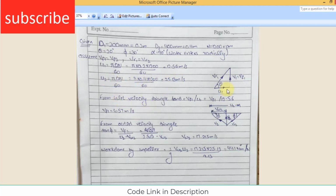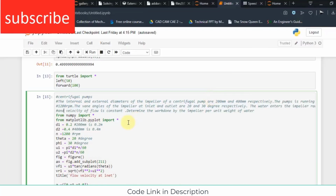Now from the inlet velocity triangle, I calculate the value of Vf1. Okay, tan theta means perpendicular upon base, so I calculated the value. I know the value of u1 that I calculated from here, and the tan theta value is from here. So I calculated the value of Vf1, and from the outlet velocity triangle tan phi, okay, I have got this value Vw2. Now let's see how to plot the graph.